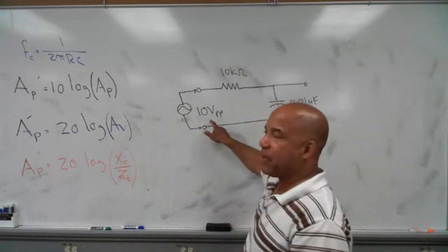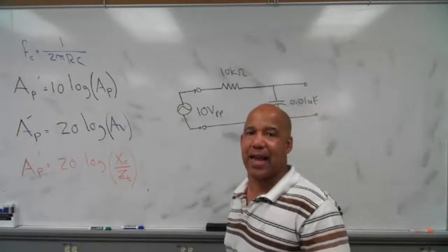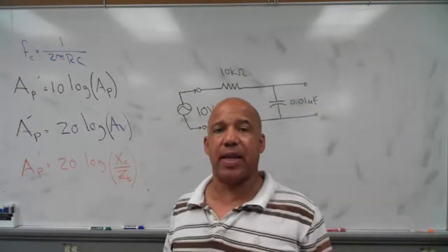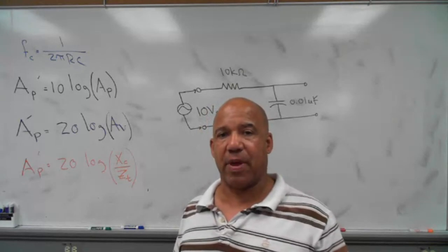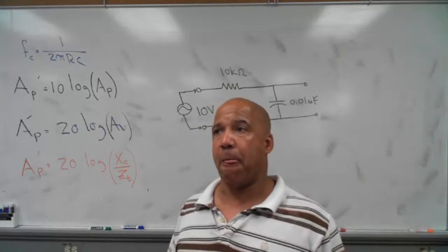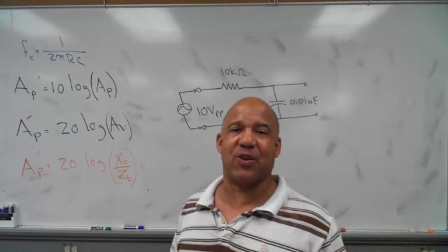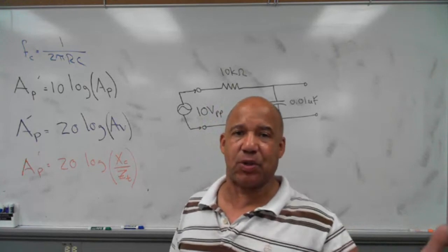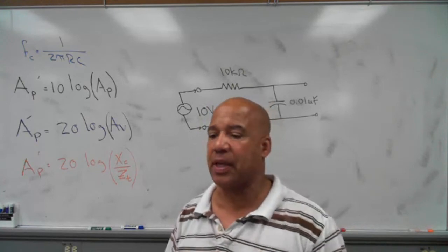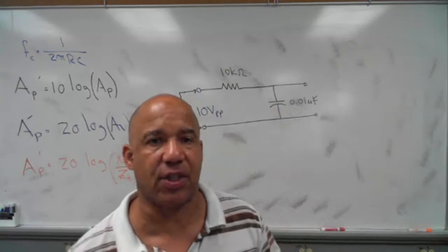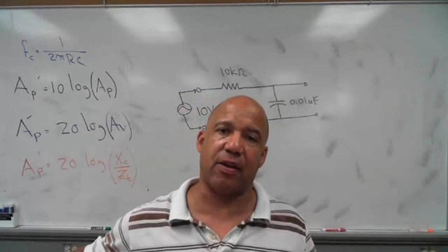They gave us the voltage in peak to peak. Now, normally when we do our analysis, we always wanted our voltage in RMS as a phasor. You call that large signal analysis. In electrical engineering, typically when you do large signal analysis, your numbers are always in RMS.